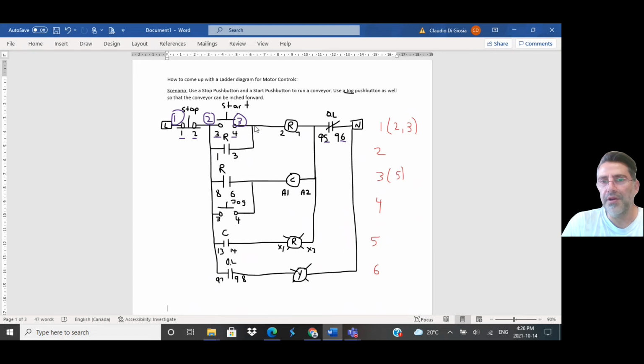So this wire here, let's say one end is on the door of the actual control panel, one is on the inside. Both ends of these wires would be wired or tagged number 3. Same thing for the relay pin 3. What I don't like to do is continue with number 4 here. A neutral is a neutral. I want to keep it kind of separate.